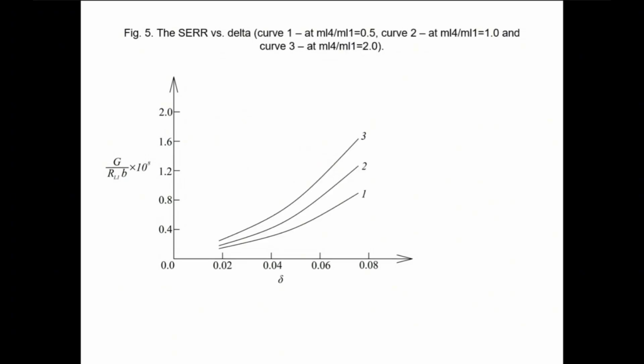So finally, it can be recapitulated that the theoretical study of longitudinal fracture in a continuously inhomogeneous nonlinear viscoelastic structure with two members rotating around a motionless axis is performed. The study indicates that increasing of L1 to L2 ratio causes a quick growth of the strain energy release rate.